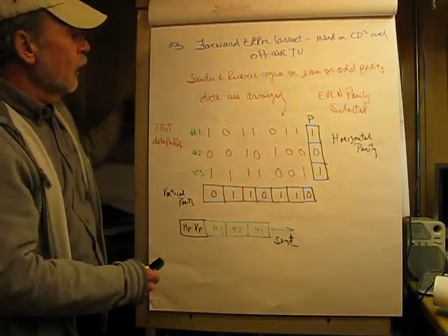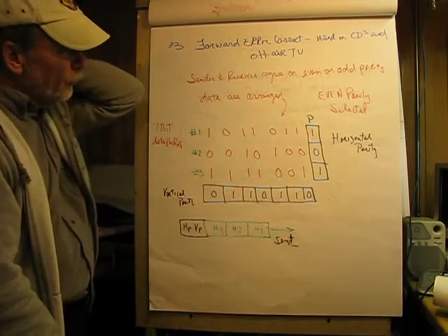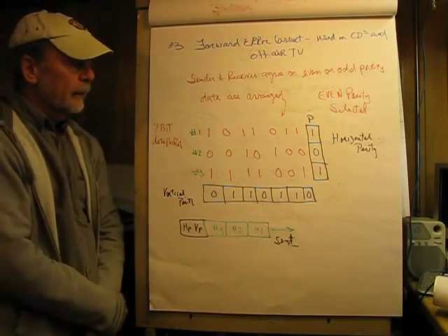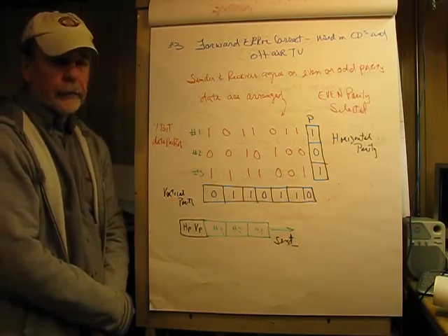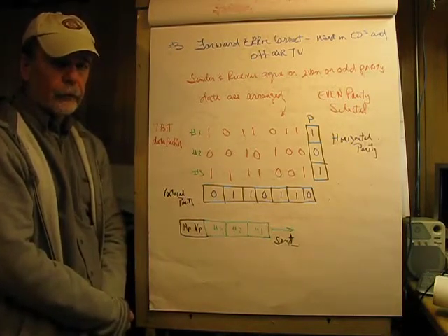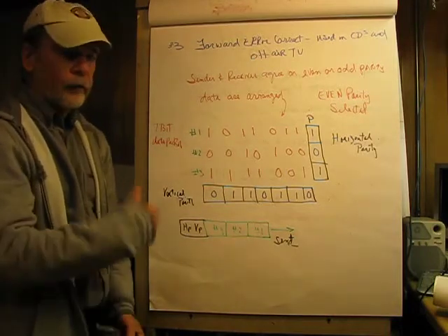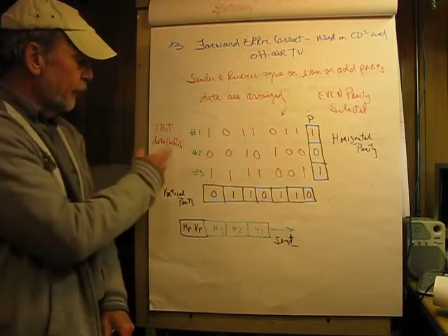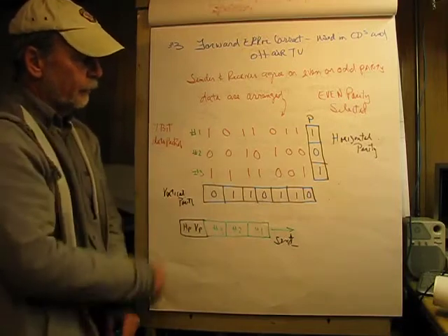Now let's talk about our off-the-air television arrangement again here, and also used with CDs, is called forward error correction. And detecting an error just isn't good enough, because in the CD, what are you going to do? Say, okay, you got some bad music here, and there's nothing to resend, it's just damaged. And in television also, the movie goes on, so to speak. So in this case, we're going to take 7-bit data packets, and this would be these guys here. I call them 1, 2, and 3.